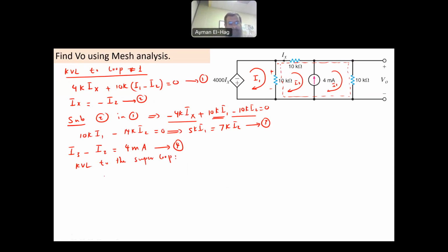We have 10K I2 plus 10K I3 plus 10K times I2 minus I1, and now I'm coming back to the point where I started, equal to 0.